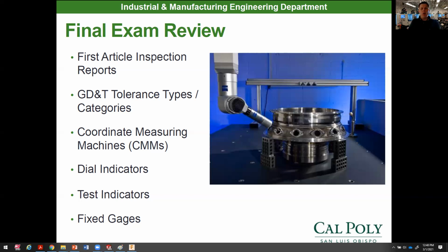If you remember, coordinate measuring machines inspected parts using computer models and probes, electronic probes, like you see up there in that picture. So I can program a CMM offline, just like I can program my CNC machine to cut parts. I can program it to inspect a part off the computer model, put it on the actual CMM, and then have the CMM automate that first article inspection and print out a report. Now these CMMs basically have 3 ways to sense parts. Not all CMMs have all 3 ways. The one in Mustang 60 has all 3 in one CMM, that MicroView.